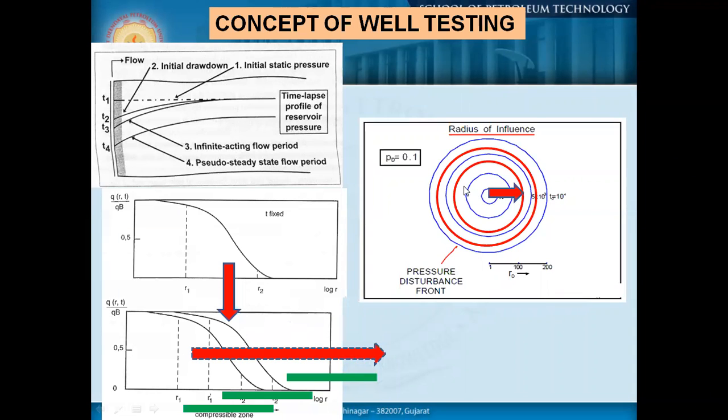So what is the main part we are trying to get from here? If we are testing a well, we are recording the pressure response with respect to time. What is happening with time is actually giving us the physical nature of that specific compressible zone, which we are recording in terms of pressure. That means if pressure is not maintained with the same Q, that area has some deviation from the normal pressure of the previous or the next domain. So this is the well test.